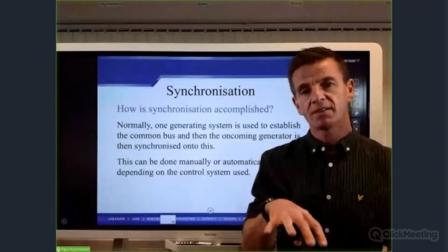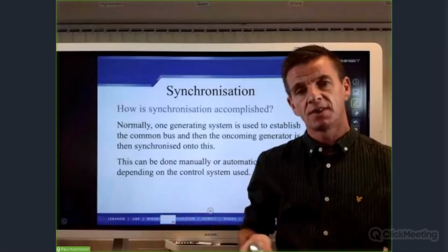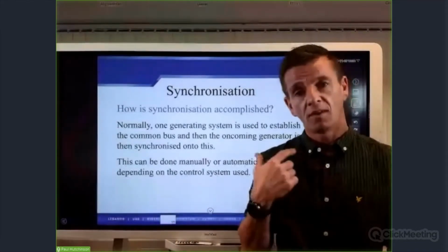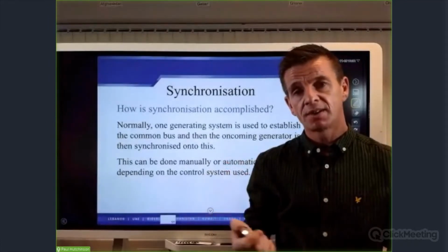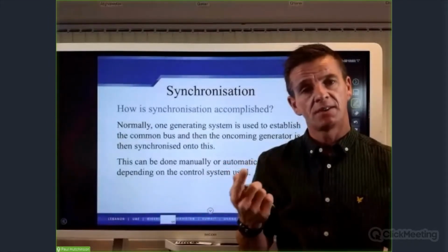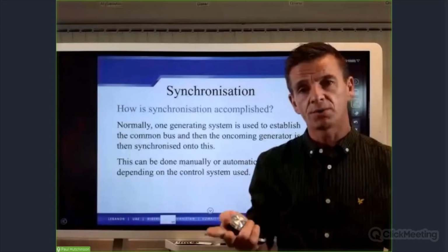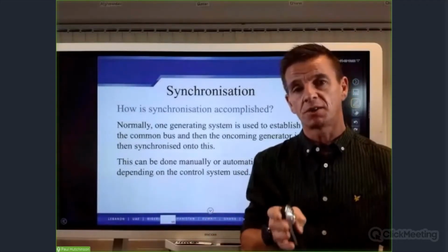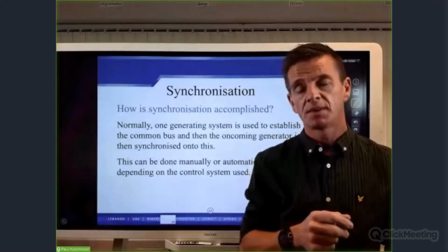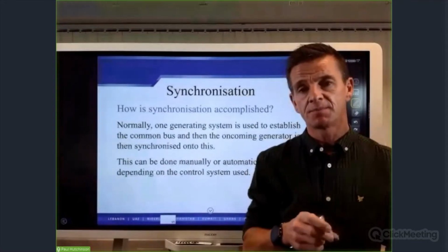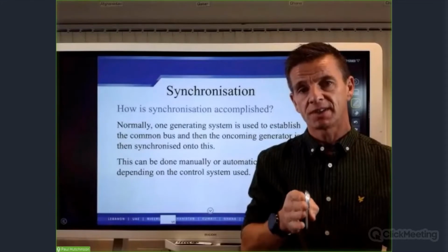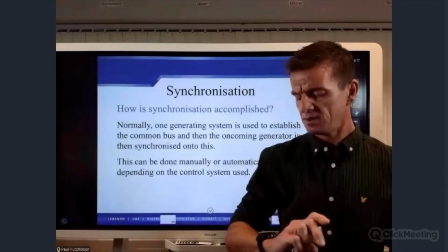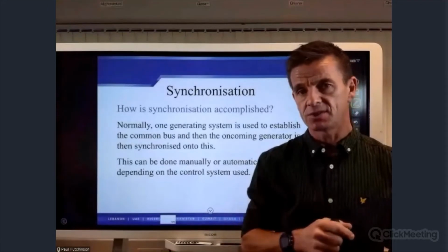Depending on the settings we have configured into it, it will do everything for us. From the moment we want to synchronize, it will take care of the speed or voltage matching, all of those things. But the one important thing that we should have done before that is individually commissioned each set. So it is important that we have commissioned each set individually.